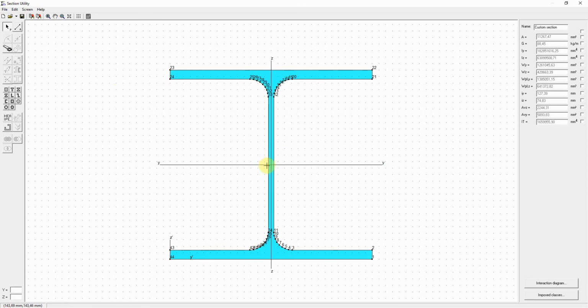We want to divide the section somewhere over here, and with this section being editable, I can select all individual lines. That means that I will select this left line and this right side, and I will divide these two lines into, for example, two pieces. Of course, if necessary, you can change the length of the two pieces in any other value you prefer.